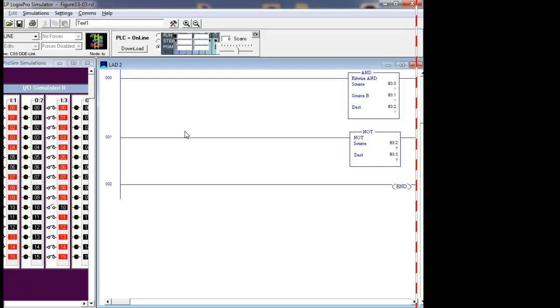So this is the way we would get our NANDs, our NORs, and our exclusive NORs. We just do it regular, and then we NOT the results. Does that make sense? So what we have now is all the basic logic plus your exclusive logic. I can do an AND, an OR, a NAND, a NOR, a NOT, an exclusive OR, and an exclusive NOR.